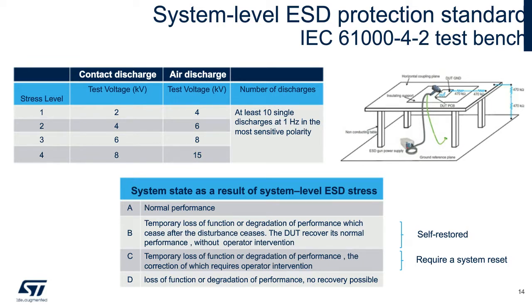The most severe level is level 4 with 8 kV contact and 15 kV air applied. The test result is rated A when the device under test performs normally without any disturbances. At ST Microelectronics, all ESD protection components comply or exceed this level 4.